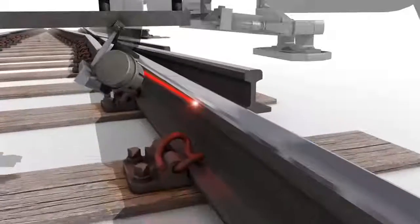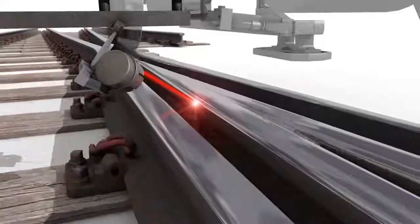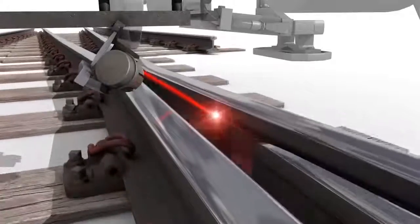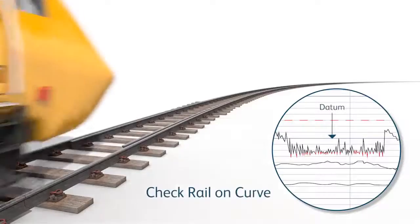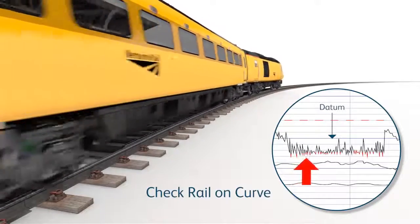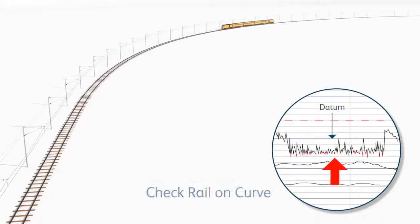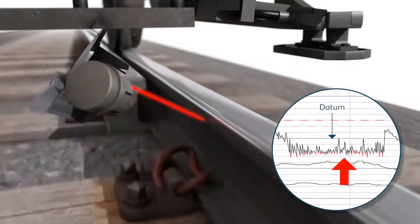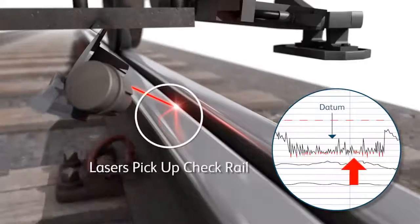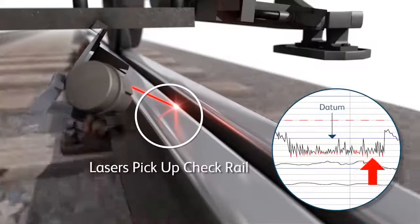Incidences of a no-fault found defect need to be reported to the section manager for further investigation and recorded on the fault report. On a tight radius curve, it is likely that a check rail has been installed. If over time the low rail on the curve has head wear, the TRV can show a length of tight gauge throughout the curve. The reason for this is likely to be that the check rail is less worn than the low running rail, causing the laser to pick up the check rail rather than the running rail.